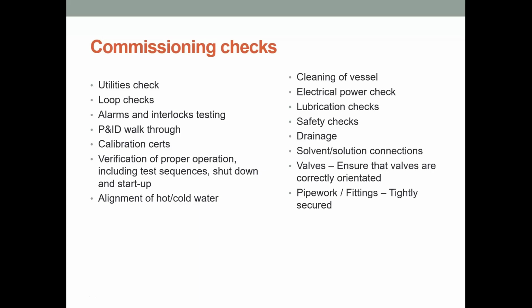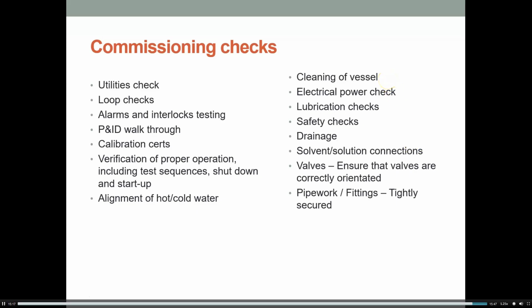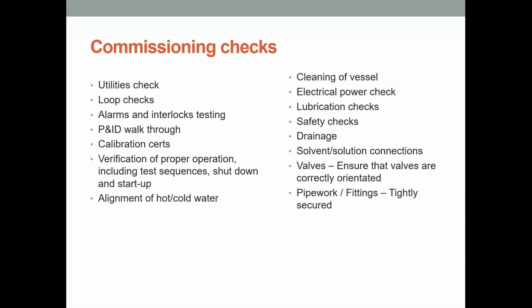We would look at the cleaning of the vessel and what it needs to be cleaned with, making sure it doesn't have any edges that are uncleanable. We would look at the electrical power to make sure it's okay and of the right amperage. We would look at lubrication, and at the safety checks, including emergency stops. We would look at the drainage of the tank, and at our solvent or water connections. We would check that all our valves are correctly oriented, and that the pipework and the fittings are tightly secured and safe.